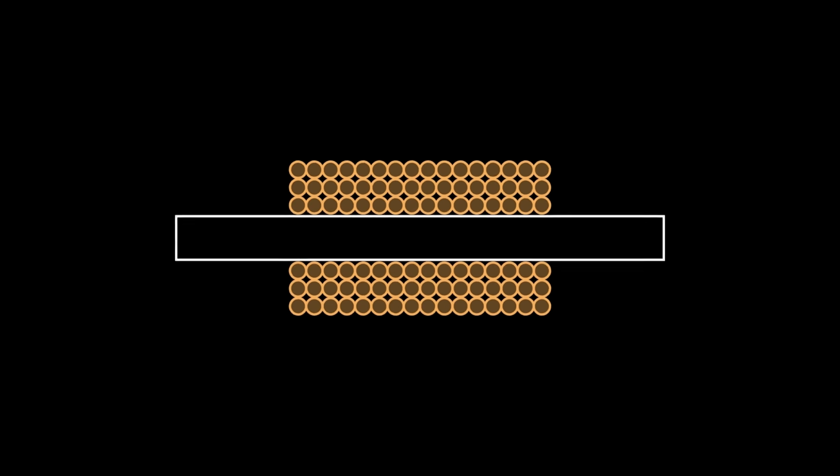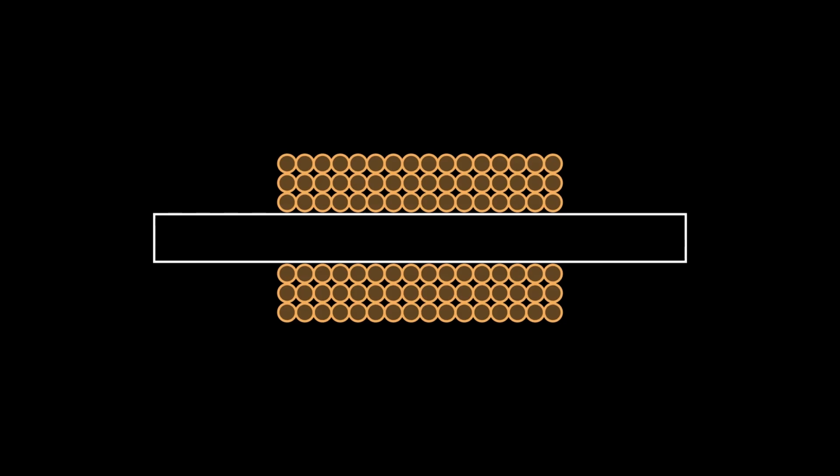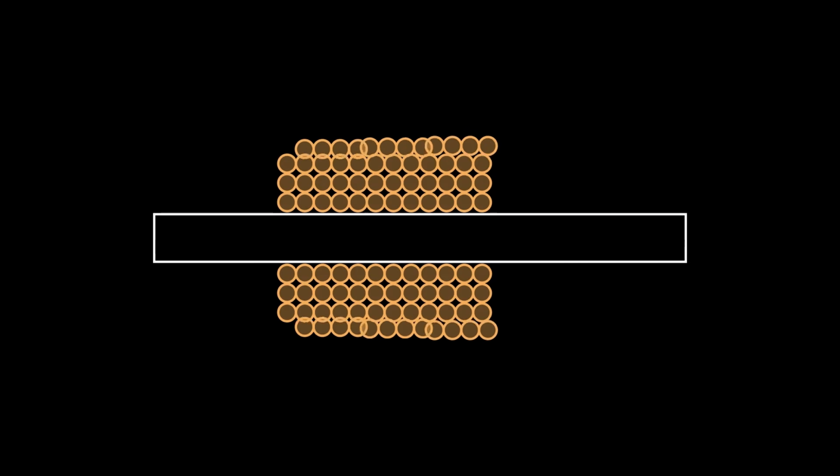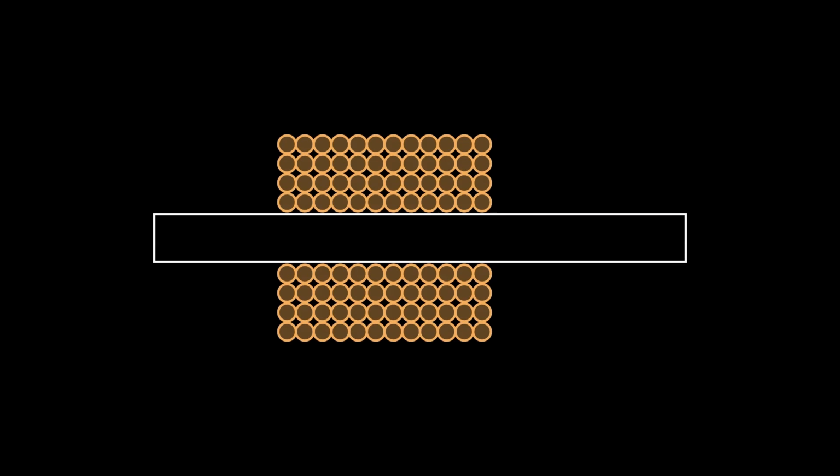To test these effects, we will start with a coil wound with the same wire as the baseline and keep the same number of turns, but shorten the length by moving the turns on the end of the coil to an additional layer. Will this shortening of the coil length overcome the decrease in current due to more wire being used to wind the turns on a large radius coil?